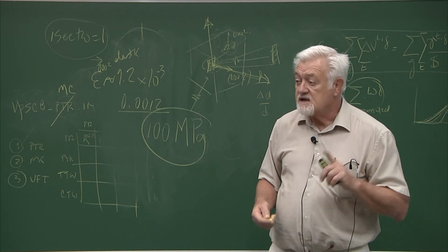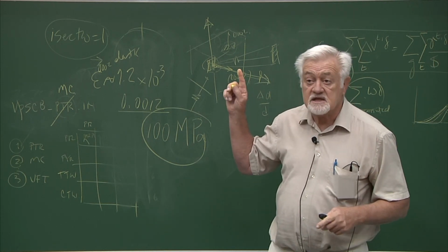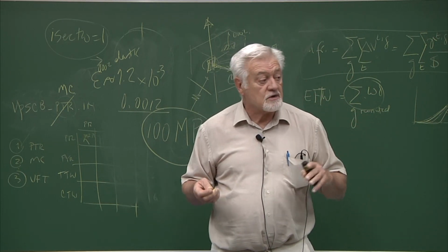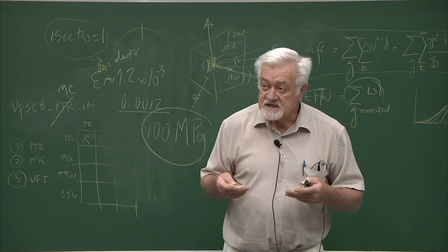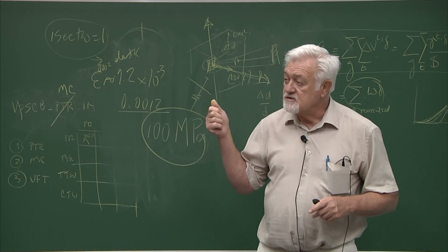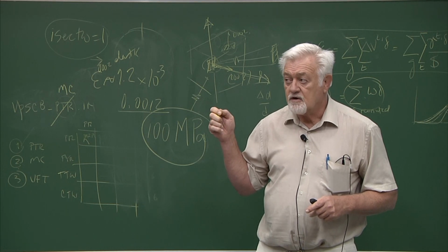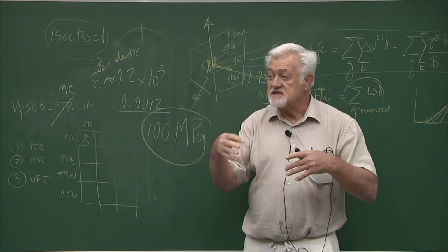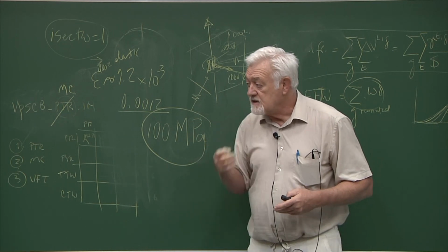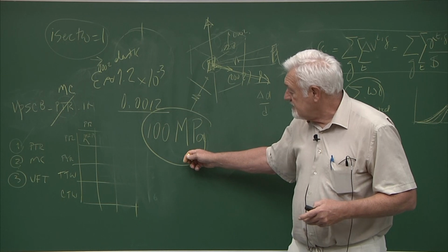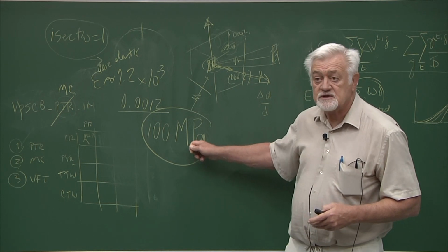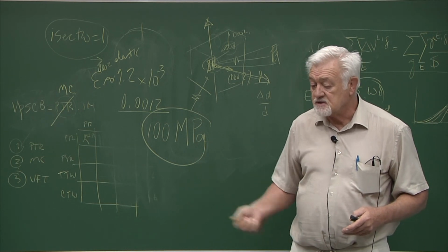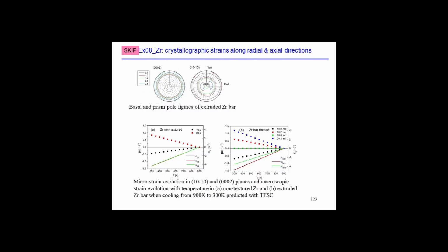Now there is a caveat. There is no plasticity in this simulation. It's only elasticity, so you force the material to accommodate all the mismatch with elastic strains. There is some amount of plastic relaxation that takes place, because when the stress increases, you activate some plastic relaxation. But nevertheless, the internal stresses stay more or less at these values, and they are consistent with what is measured experimentally.